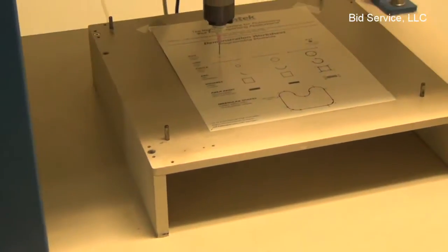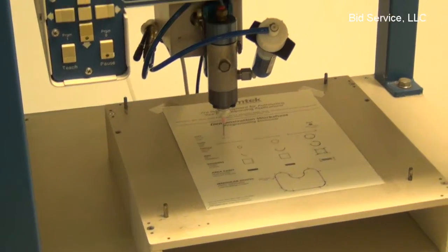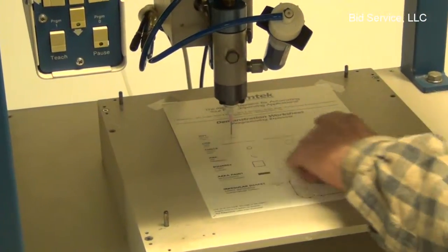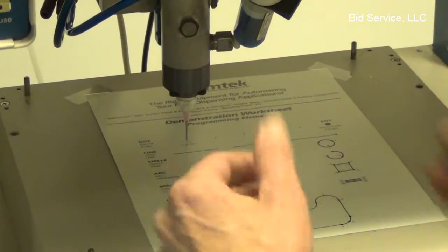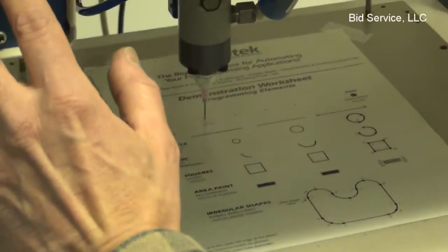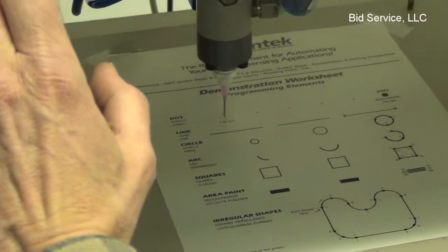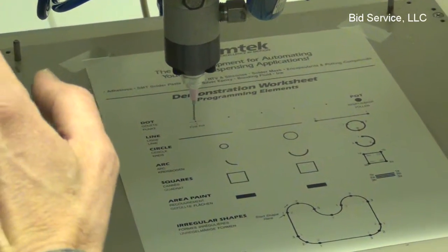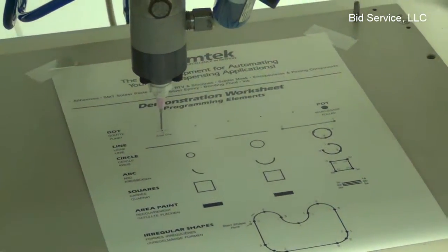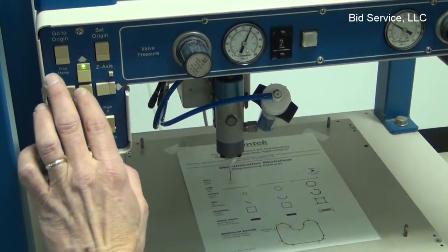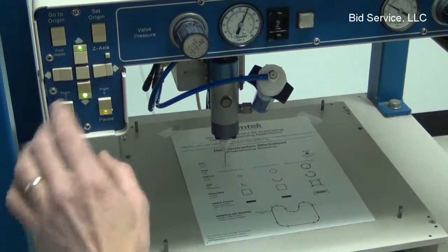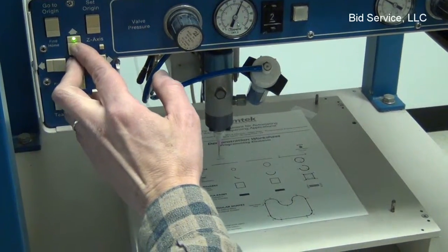Now it's going to look for the fiducials that I set up. I set the first point here and this point here as the fiducials. If you have to readjust as you change your pieces, you can by moving your X or Y. If you want to do Z axis, you can just move it up or down like that. The center button will increase the speed. You've got to hold both.